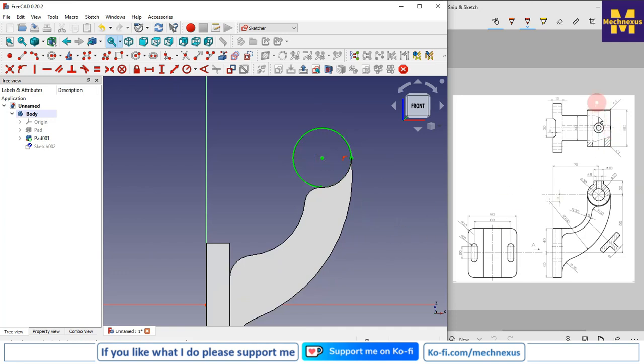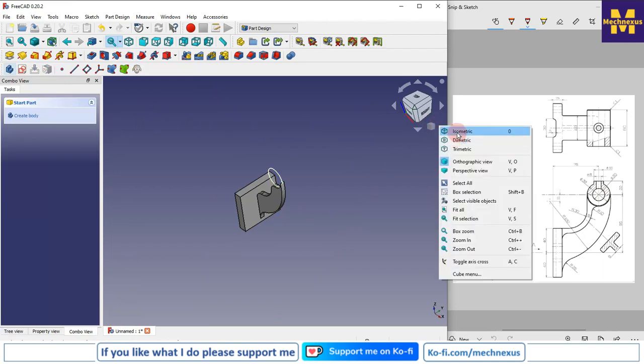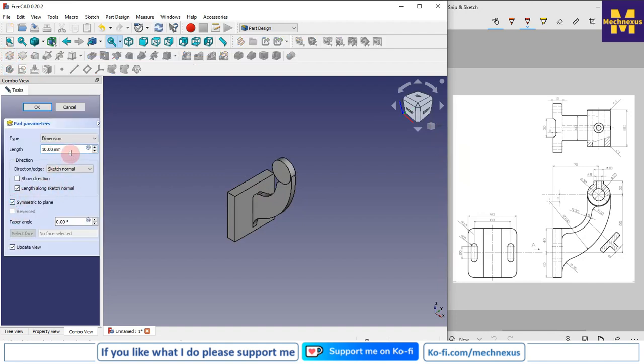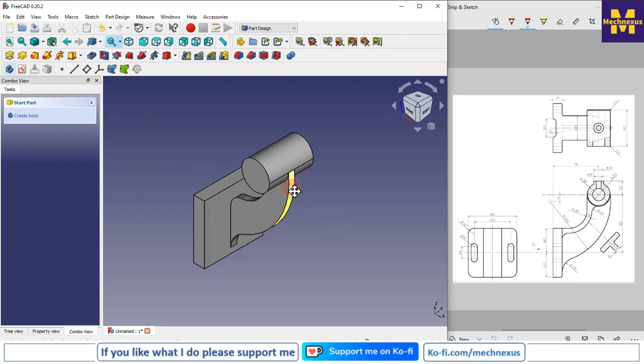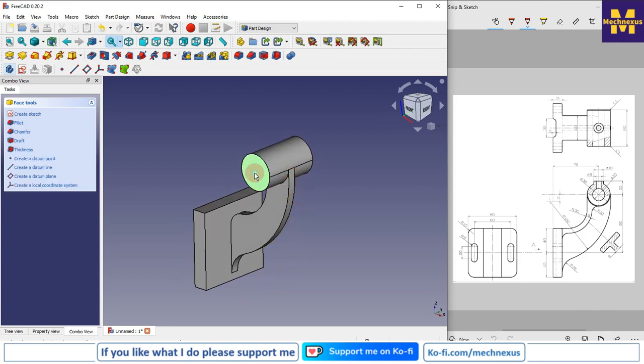Now if you see in the top view, the extrusion length of this circular boss is 60. So I will come out of the sketch and click on the pad and click on symmetric to the plane and give the 60 mm, right? And now we will make this cut later. Now we will make this feature.